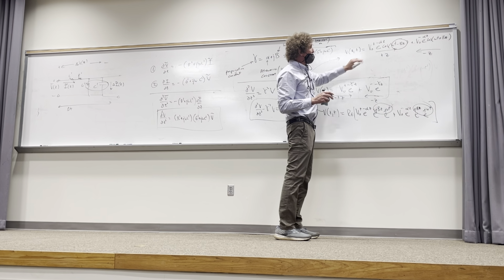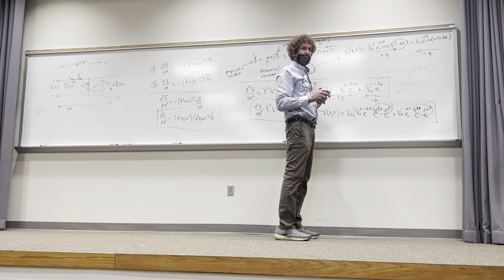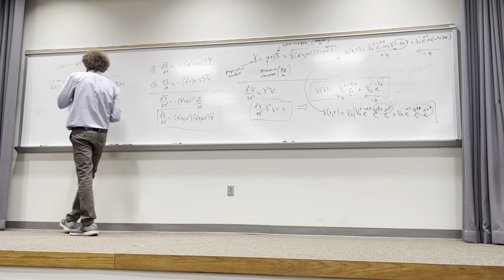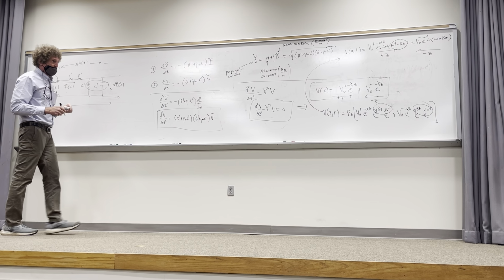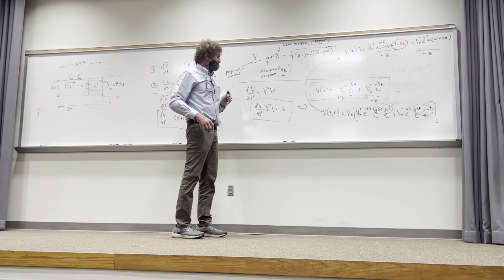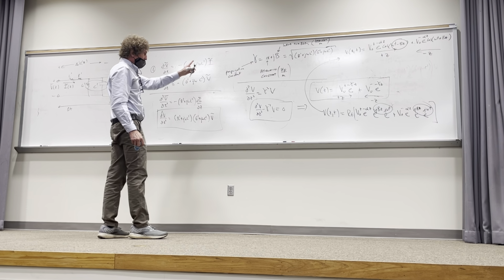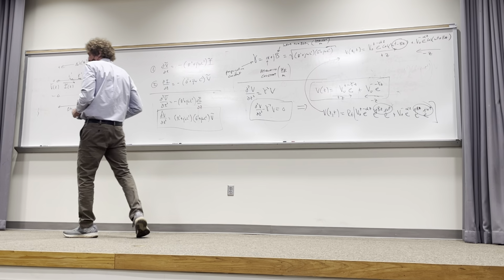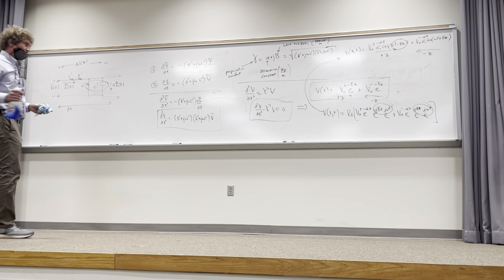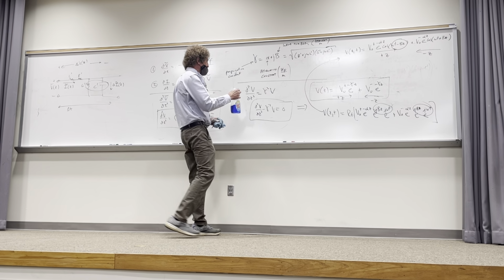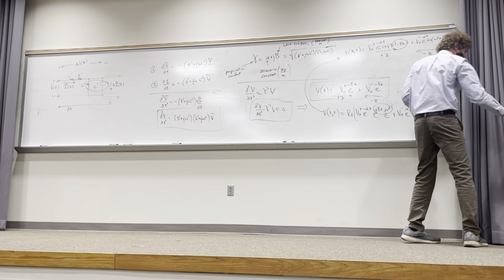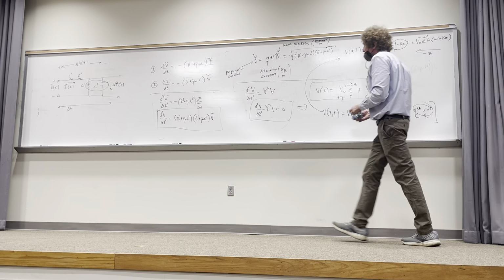Anyway, that's the general form of the solution that you get from the assumption that we're at a constant frequency, and this is the model of the transmission line. I'm going to tell you one other thing, and I'm going to use this middle board to do it. You did everything with respect to voltage V. That's the voltage difference between the upper and lower contact point on the transmission line.